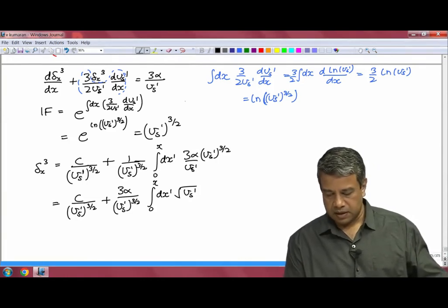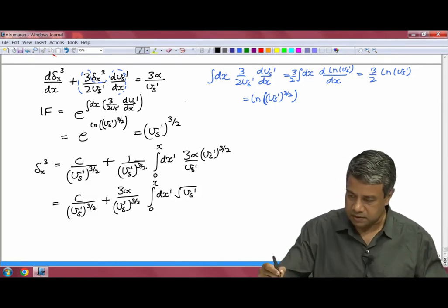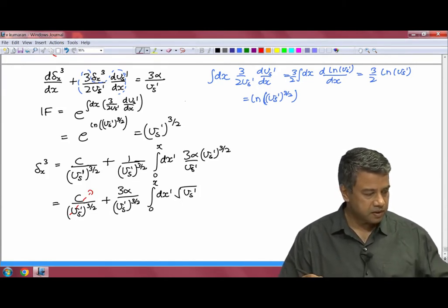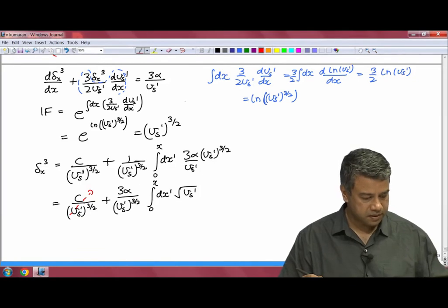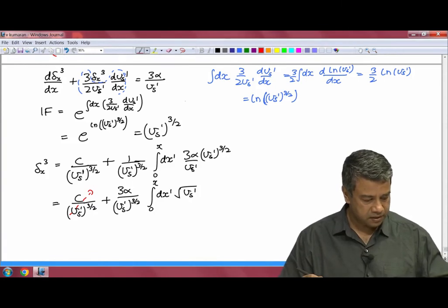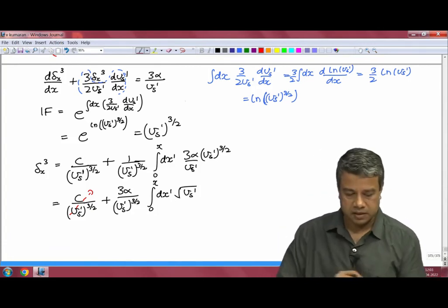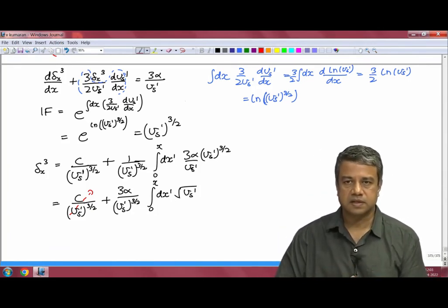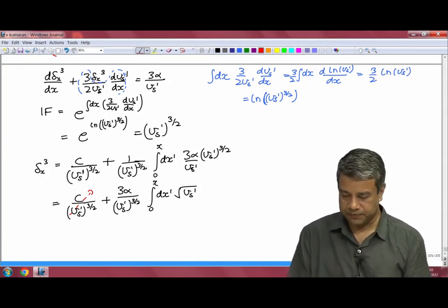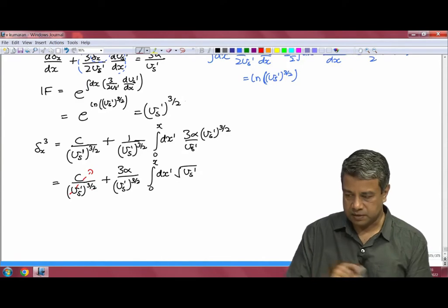Boundary layer thickness, and if we assume that the boundary layer thickness is 0 at x is equal to 0, that means this constant has to be equal to 0. So, this is the general solution for the flow past a surface at which you have a no slip condition, that is the velocity decreases to 0 at the surface, flows past rigid surfaces such as a particle or a flat plate and so on. And you recall that we had done two problems here. One was the flow past a flat plate.